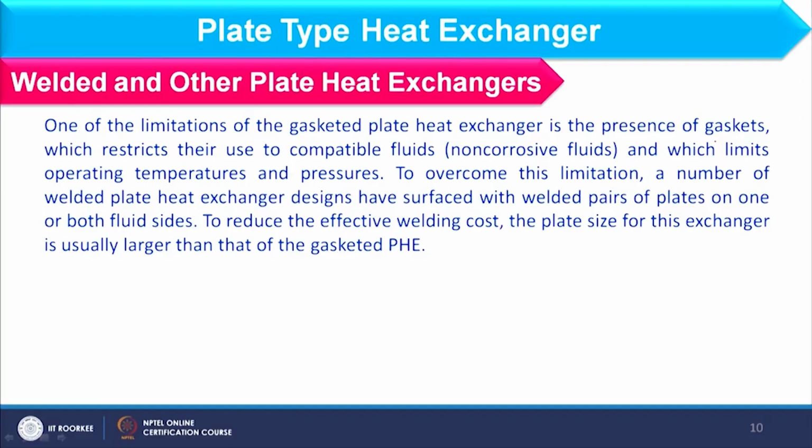Welding is done when we are dealing with highly corrosive fluid, or with high temperature and high pressure fluid. Again, we have a disadvantage with the welded plate, because it is permanently joined. So, that will be difficult for cleaning purposes. These are basically the advantages and disadvantages, and in which case which type of plate heat exchanger should be used, all these we have already discussed.